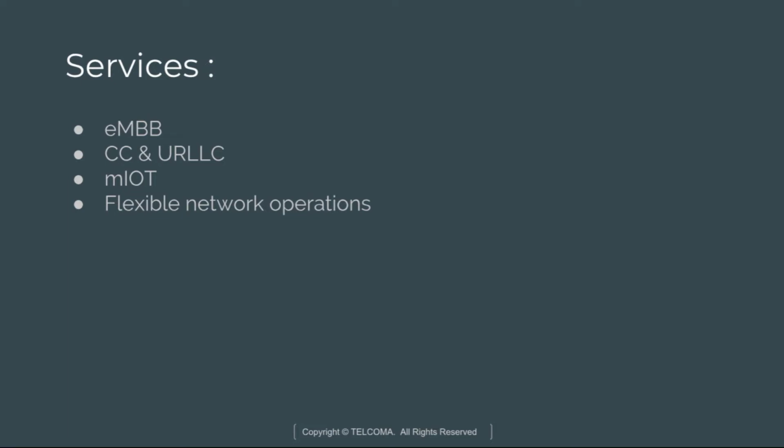and coverage scenarios. The scenarios address different service areas: indoor, outdoor, urban, rural areas, office and home, local and wide area connectivity. And there is also a need for special deployments, for example, massive gatherings, broadcast, residential and high-speed vehicles. For the performance requirements, for downlink, an experienced data rate of 50 Mbps is expected outdoor, 1 gigabit per second indoor, which is 5G LAN, and half of these values for the uplink.